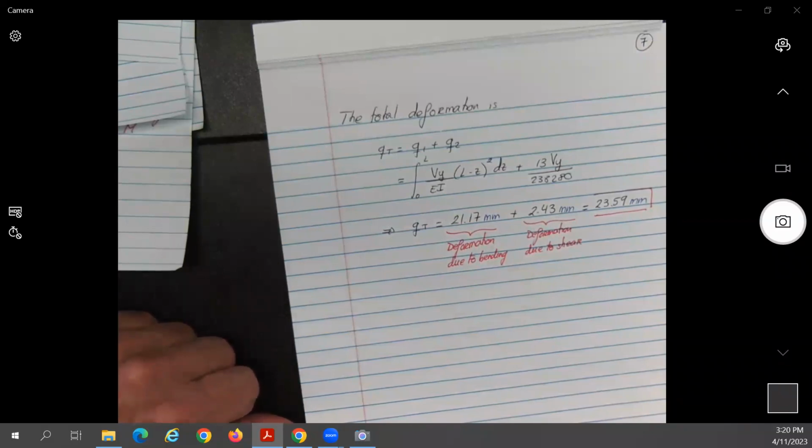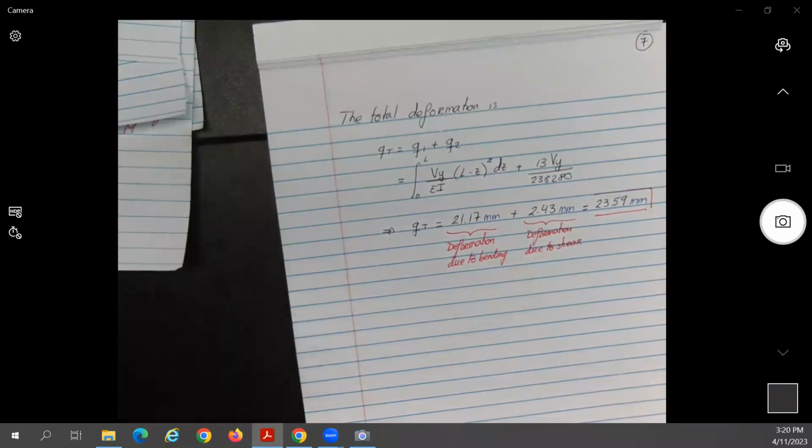Let's say there's one component on the aircraft, one item that is repeated multiple times. What do you think it is? Rivets. Okay, exactly, rivets. So for example, to calculate the number of rivets that you need to put for each panel, how do you think you calculate it? By looking at the shear flow, no? So you know between this panel and this panel is that much shear, no? And let's say you know that each rivet can support a certain force, no?